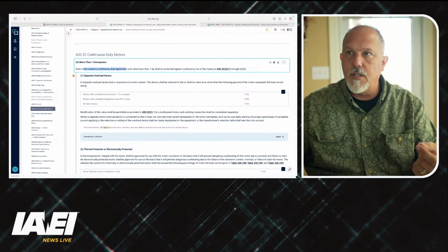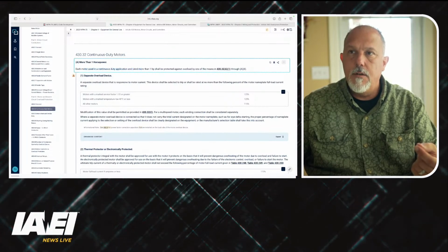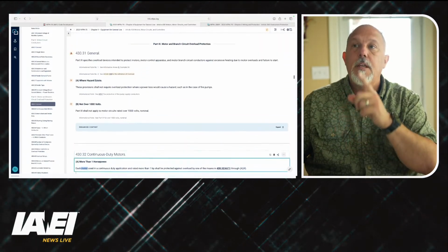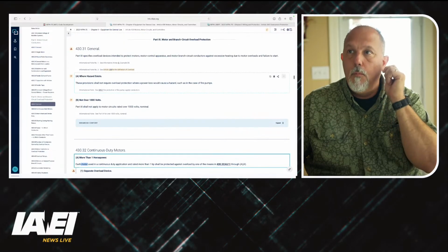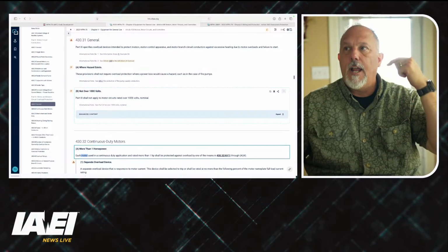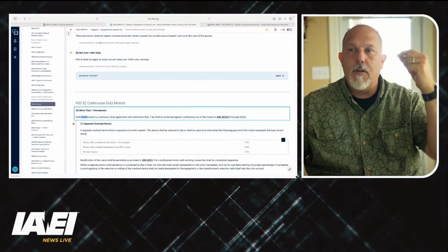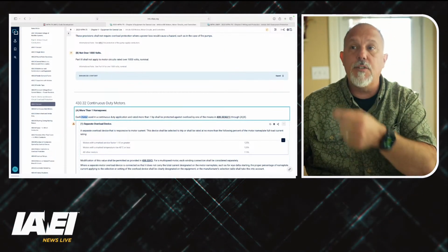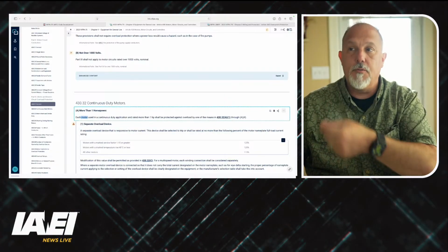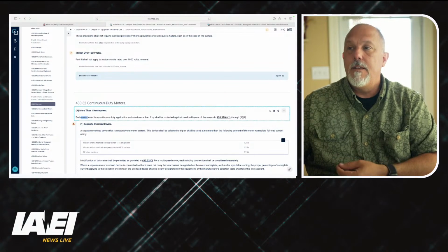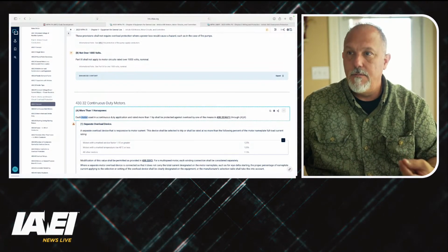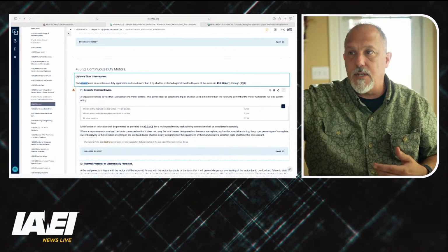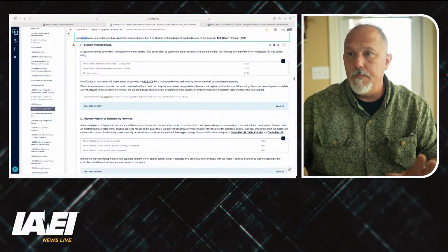Each motor used in continuous duty applications. Now, if this would say each motor, motor control apparatus, and motor branch circuit conductors that are applied for continuous duty applications, and where the motor is more than 1 horsepower, must be protected by overload, and by one of these means, then I'd be okay. But now, when I'm looking at the values, I see 125%. I don't have a problem with that.